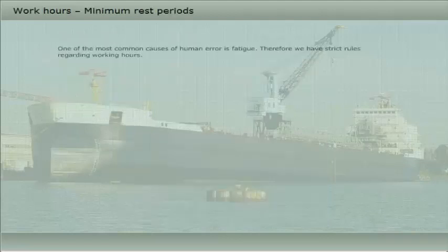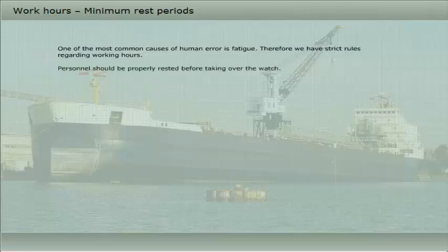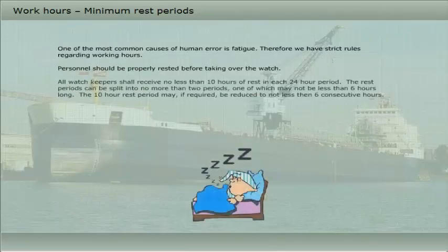One of the most common causes of human error is fatigue. Therefore, we have strict rules regarding working hours. Personnel should be properly rested before taking over the watch. All watchkeepers shall receive no less than 10 hours of rest in each 24-hour period. The rest periods can be split into no more than 2 periods, one of which may not be less than 6 hours long.